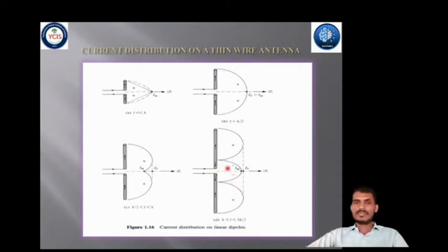See, here is a plus, here is a minus, and here is a plus again. So this undergoes 180-degree phase reversal between adjacent half cycles. These two half cycles cancel each other, and these two half cycles cancel each other also. In turn, the field radiated by some parts of the dipole will not reinforce those of the others. As a result, significant interference and cancelling effects will be noted in the formation of the total radiation pattern.